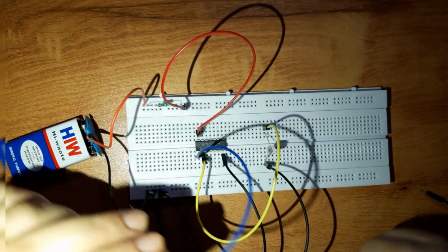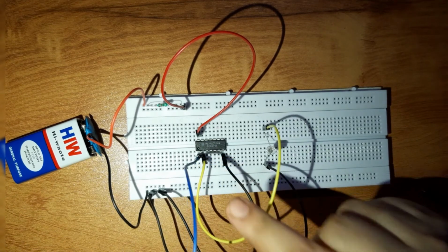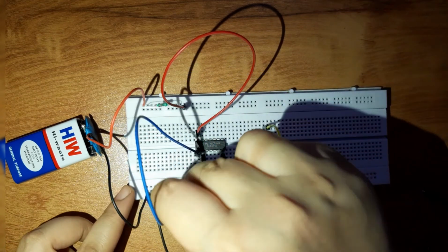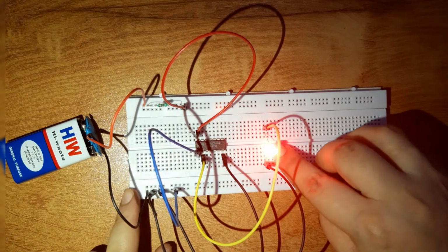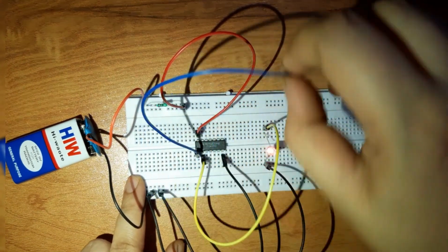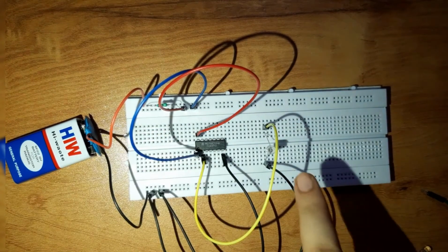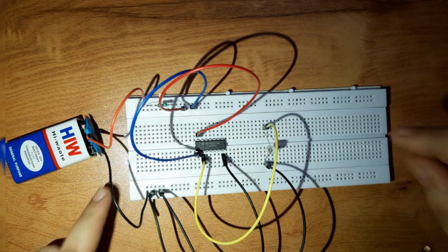So right now the input is high because it is open and which is in air. So if I'm going to put this input to this 0, it will invert this input and the output will be high. So if this input is going to be 0, that is negative, the output will be high, and if the input is going to be high, the output is going to be low. So this is how the NOT gate is to be implemented.